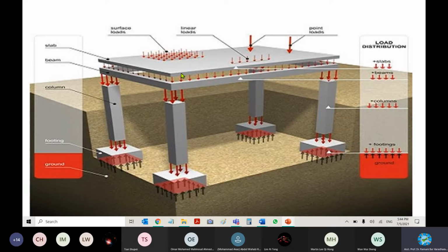The point of the slab acting on the beam: if you see, the type of load is a distributed one, right? It acts over the whole length of the beam. The two bodies are in contact, exerting a load over the length. On top, only a small strip is acting, but later on it is distributed based on the material property. You will get a stress distribution accordingly, and also the concentrations, right?